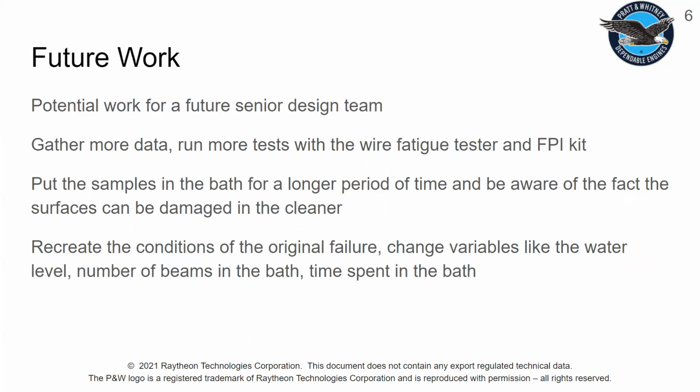So in the future, we left off at a great point for another team next year to pick it up. They already know the procedure that they will be following. They will be just putting the wires in the bath and then in the fatigue tester. There are some things to note though. You have to be careful because if the parts are in the bath, they could scratch and damage the surface, leading to results that we don't really want. We want to focus more on the vibration caused by the bath itself.